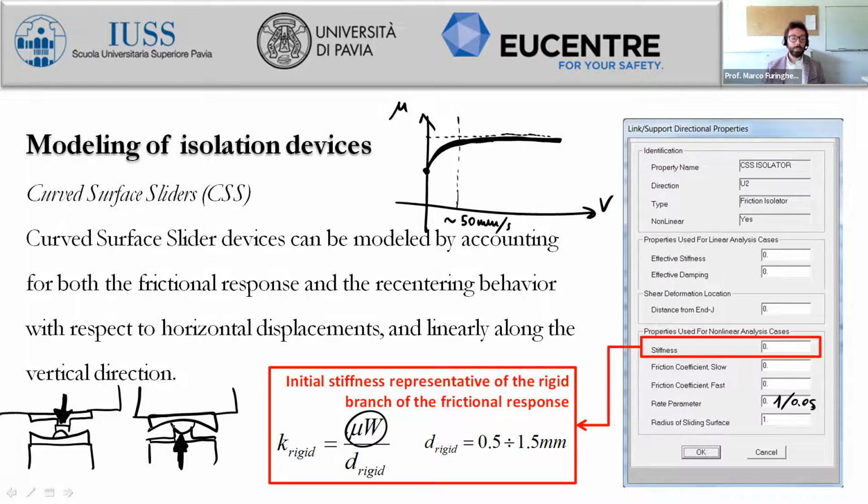So yeah, I see your point, but I think that this is quite difficult to model, I mean, dynamically. What we can do is to consider just the fastest analysis that we can have from the time history point of view, so without accounting for the P delta effects.